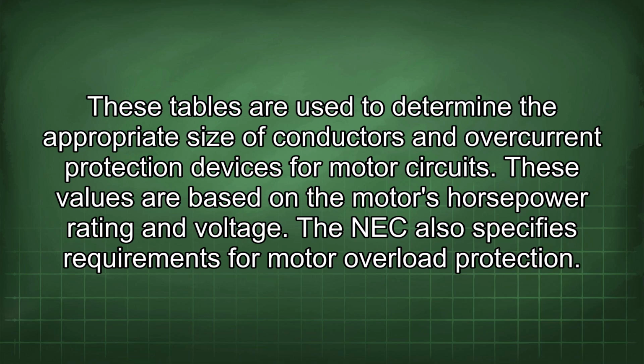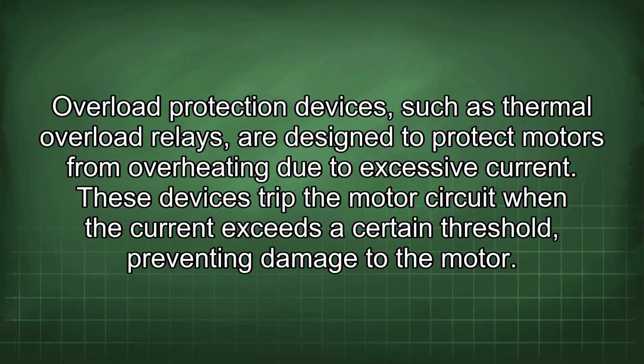The NEC also specifies requirements for motor overload protection. Overload protection devices, such as thermal overload relays, are designed to protect motors from overheating due to excessive current. These devices trip the motor circuit when the current exceeds a certain threshold, preventing damage to the motor.